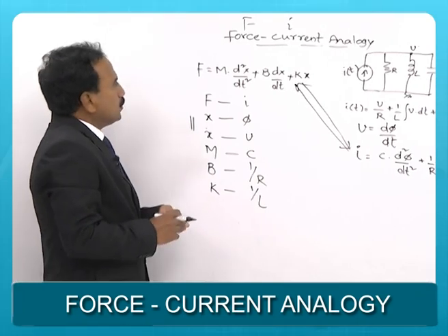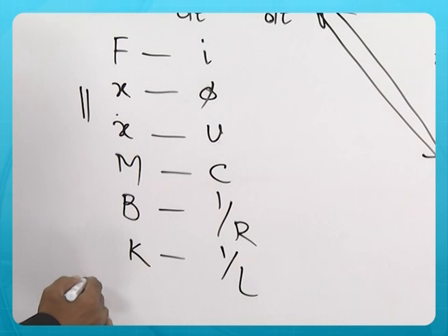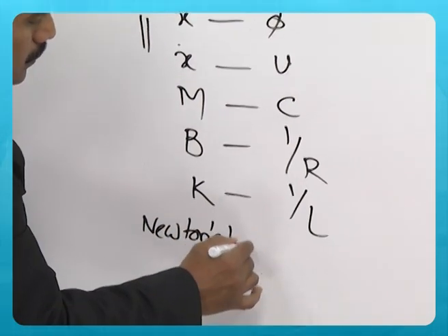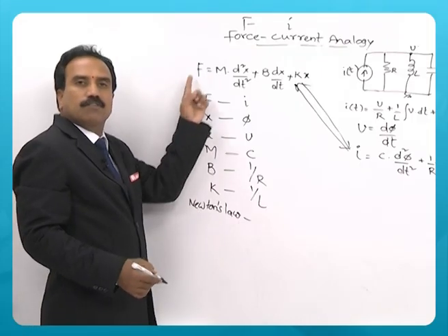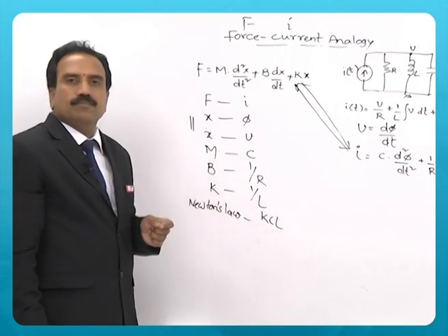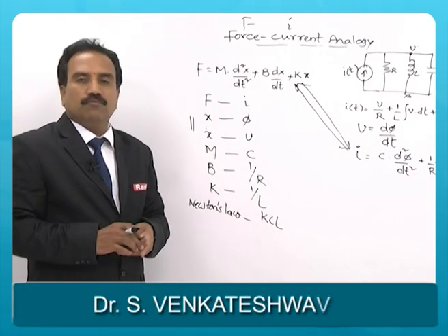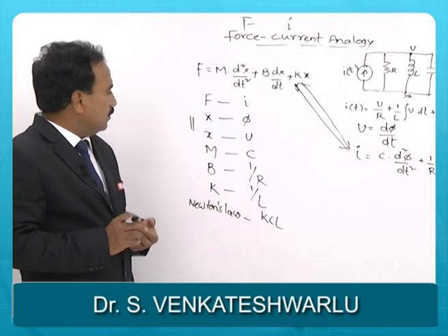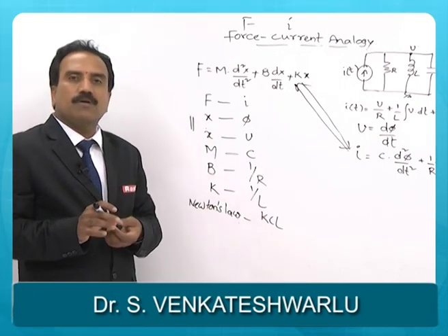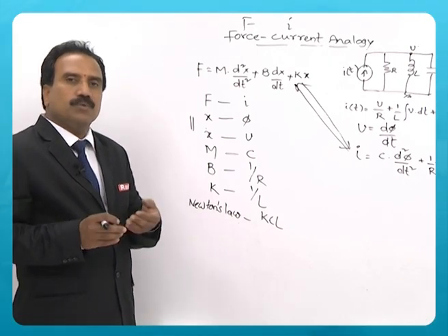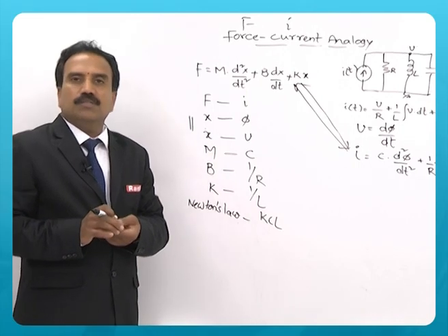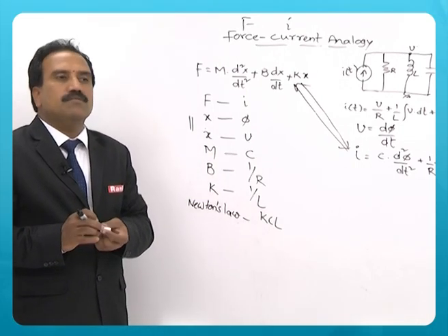So, which law again? Here, as I said, Newton's second law of motion is being used to write the equation, and here we use KCL, unlike KVL in force voltage analogy. So, that way you must be thorough with the basic laws or basic principles to write the required equations. Applying Laplace transformation and getting the transfer function is very easy.